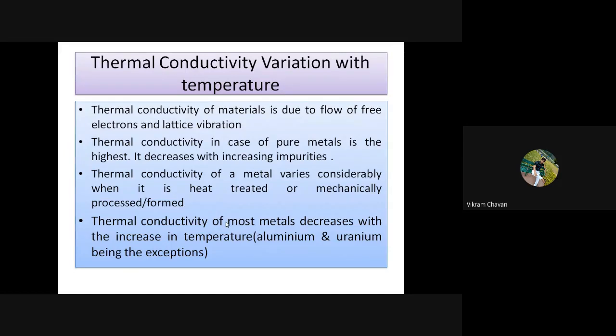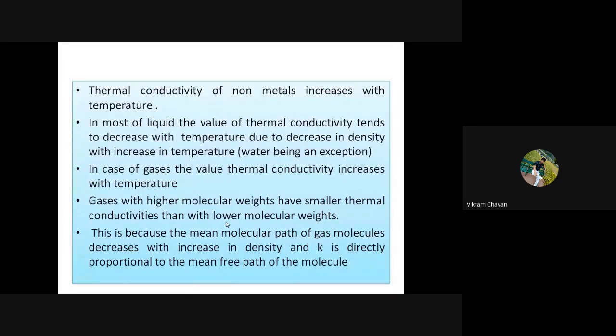And then next, in case of non-metals, thermal conductivity increases with temperature. Okay, opposite to metals, that is non-metals. Why is it happening? Because in case of non-metals, free electrons are not available to transfer the heat. The heat will be transferred because of lattice vibration only.